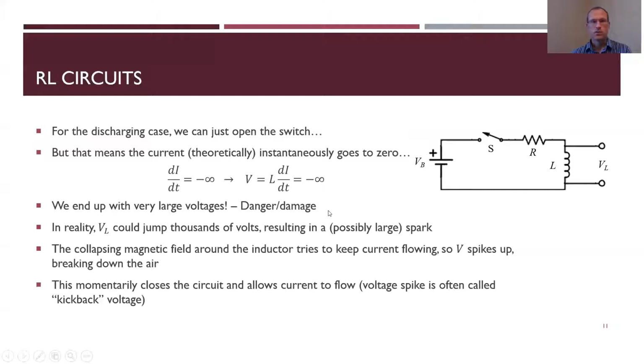So that is a danger in having an actual physical switch that you open and close with an inductor, because even if your time is not 0, it still can be very small. And if it's very small, you're still going to get a very large voltage out of this. And if you get a very large voltage while you're holding onto a switch, it's generally not good, things are going to happen.